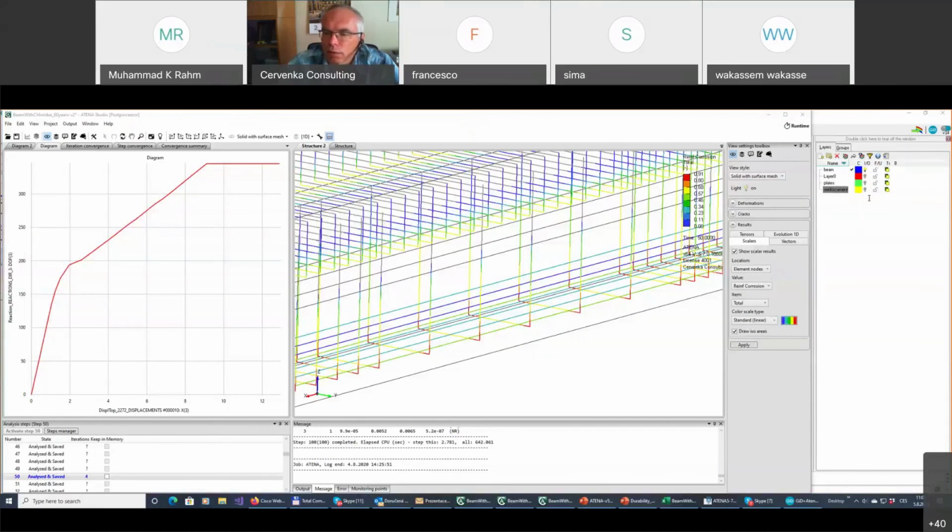I just want to give you an understanding that, of course, this approach considers these effects. Right now, we are not simulating this exactly. By that I mean we do not, as the reinforcement corrodes, of course it expands, and this expansion should introduce some initial strains in the model, and this we do not consider. We consider it, let's say, indirectly.